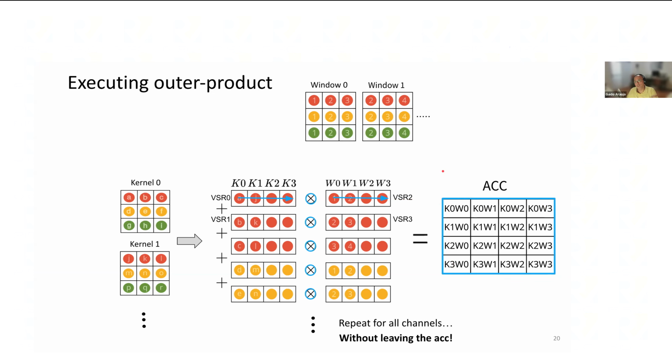So there is a trade-off in the hardware design for this, right? Should I do a systolic array, which has some complexity but probably is going to have a faster clock cycle, or should I do a matrix multiplication where the gates are going to have a larger fan-out, and you might have a little bit larger area, but it's going to be faster somehow. That's a hard design choice that I didn't want to discuss here.